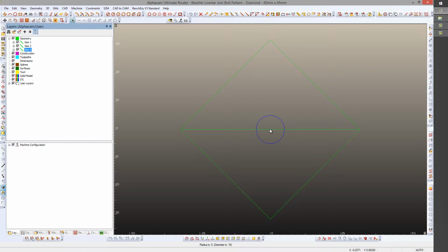BenchEzy will check each template for you as it's throwing it into a benchtop to make sure that each template only consists of 3 geometries. If there's 2 or 4 or more geometries, BenchEzy will throw an error and say that your joiner bolt pattern is incorrect. You will not be able to proceed with that joiner bolt pattern until the pattern is fixed to meet the BenchEzy requirements.